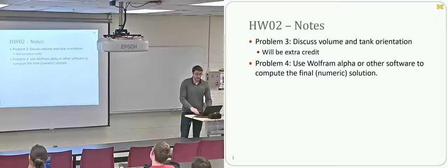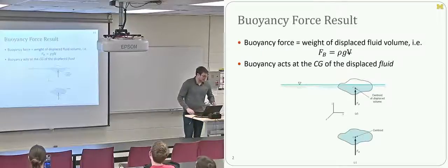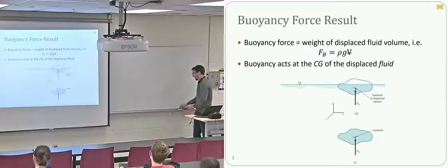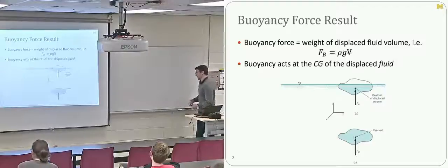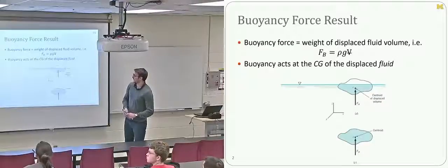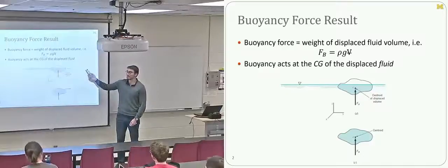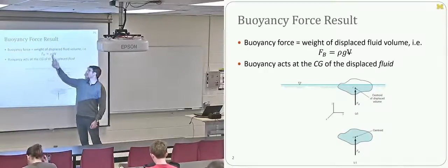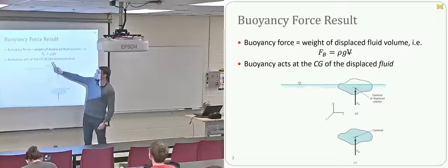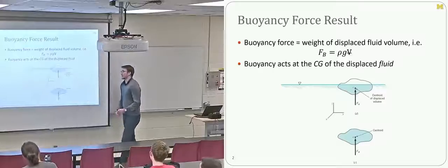Are there any other questions that have been cropping up on the homework that's due Friday? Okay, so we almost made it through learning why things float, which is a good thing, on Monday. We went through the process of, for the case of a circular cylinder, showing that the buoyancy force is, as Archimedes postulated, equal to the weight of the displaced water, that is rho g times the displacement volume.